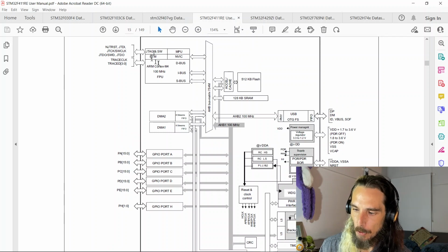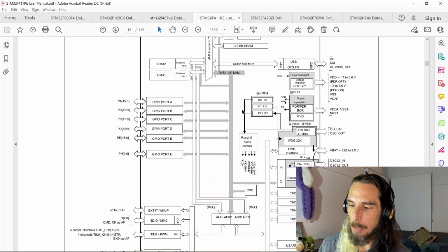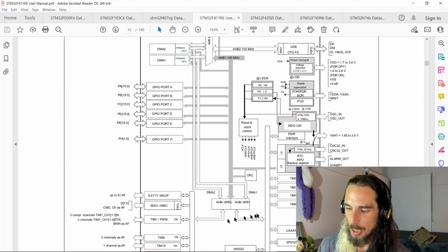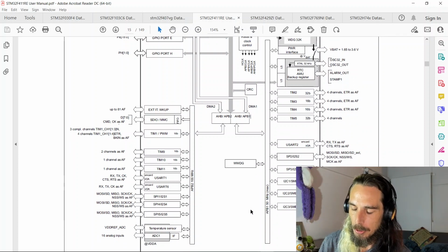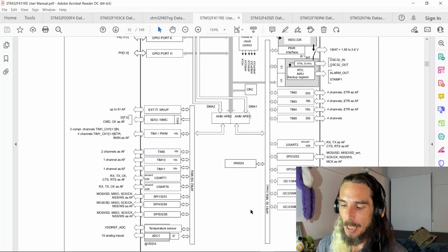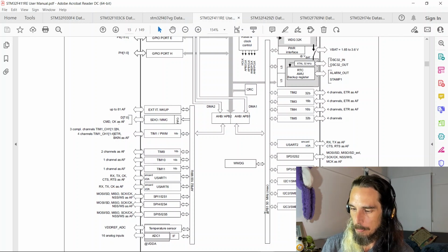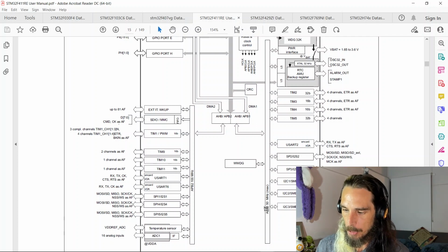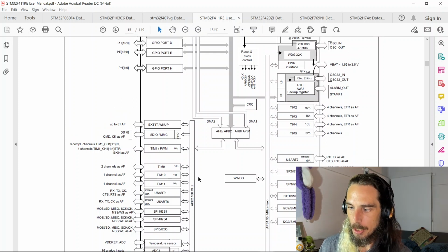So you'll have most of your faster stuff connected to a bus matrix. You'll have a host bus, which is connected between the bus matrix and the bridges, which then go off to the peripheral buses. And in most of the devices, except one that we're looking at here today, there's only 2 peripheral buses that you'll have to deal with. You've typically got APB1, which in most of the devices is going to run at half the maximum speed of the CPU's maximum. So in this case, maximum 50 megahertz for APB1. And then we've got APB2, which can operate at up to 100 megahertz.